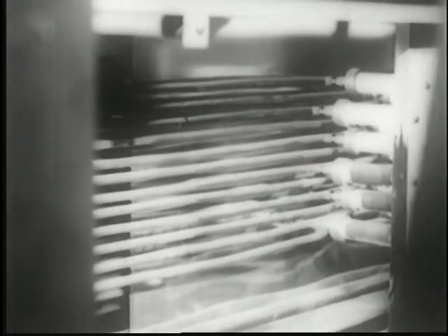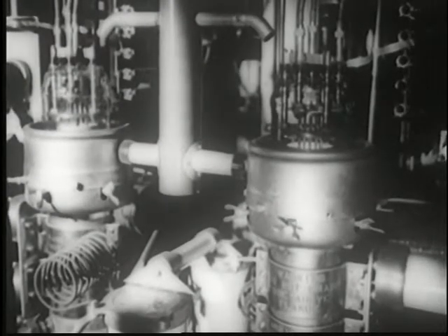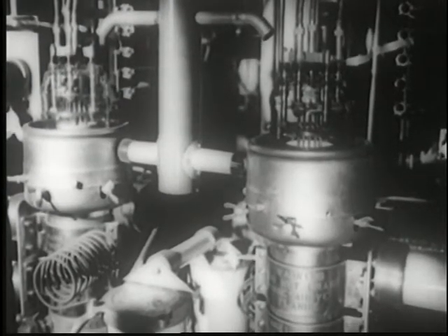Note the horizontal bars in this close-up. These are parts of one of the high-frequency coils that affect the tin flow. If you look closely, you can see the difference in texture between the porous tin entering the top of the coil and the shiny flowed tin leaving at its base. And these are the tubes that generate the high-frequency current which makes the entire process possible.